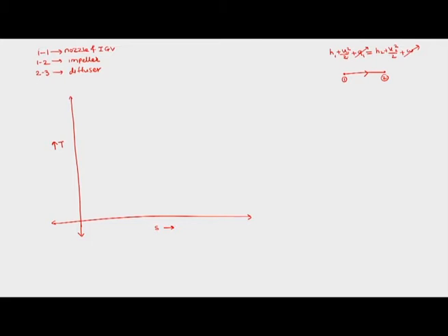The velocity of the flow will become 0, and then that velocity which is decreased to 0 would help to rise the enthalpy. So for station 1, if we isentropically stop the flow in an imaginary manner, then we will have h1 plus V1 square by 2 is equal to h01. So this is the stagnation enthalpy for the station 1. So h is called static enthalpy.